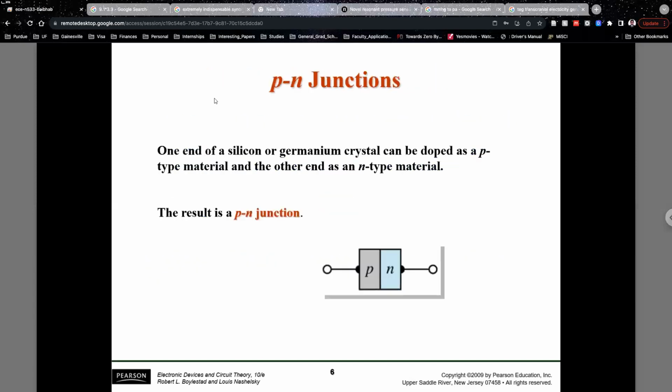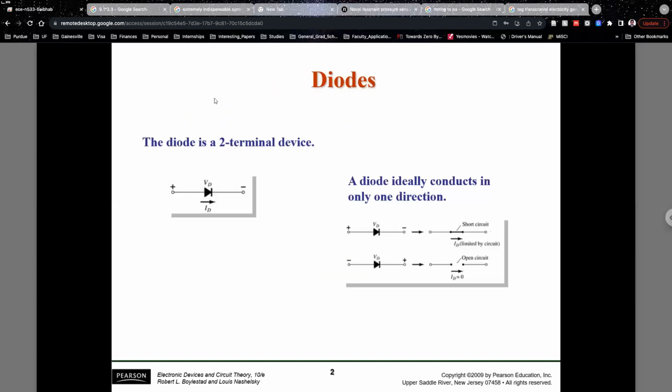So that's the property of electronic switching. Now we'll go into the details of what a PN junction is and why, when you apply the positive voltage to the P side and the negative voltage to the N side, you have a forward bias diode. And if you do the vice versa, you have a reverse bias diode. We'll get into the details of that. But I just wanted to be upfront with the applications of the diode, that this is what you eventually want to do with any diode. You forward bias it, you get a short circuit. You reverse bias it, you get an open circuit. So that's the primary application of a diode in any circuit.